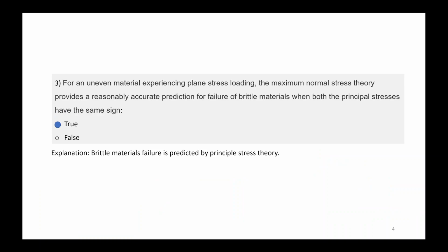For an uneven material experiencing plane stress loading, the maximum normal stress theory provides a reasonably accurate prediction for failure of brittle materials when both the principal stresses have the same sign.